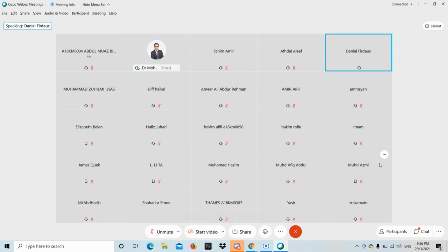Okay, this is how it works, Daniel. Engines are designed for RON 97. Engines don't know what the fuel is. They can only behave according to the calibration or programming that the manufacturer has done. So if the engine is calibrated for RON 97 and you fill in RON 95, there's a possibility that knocking might happen.